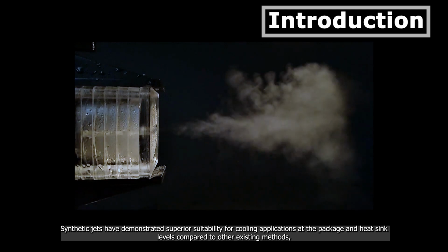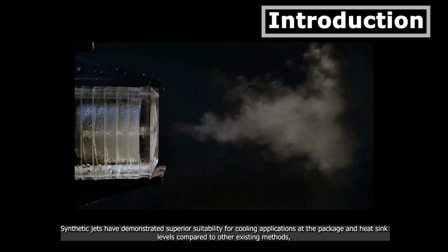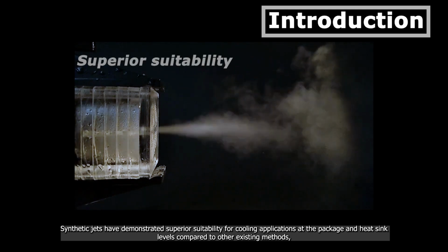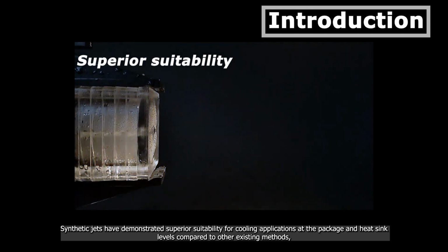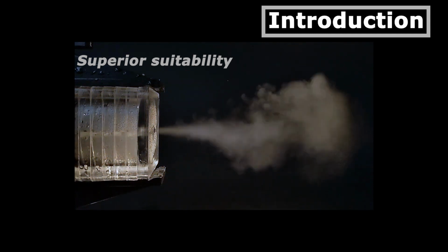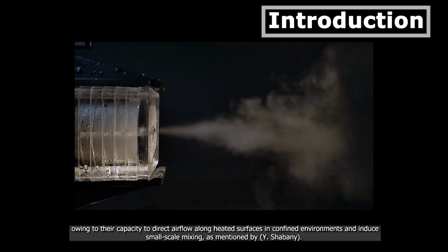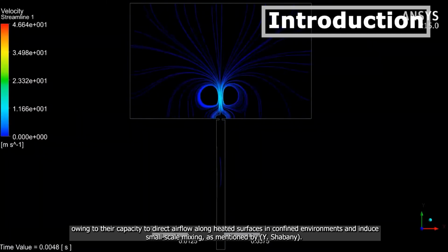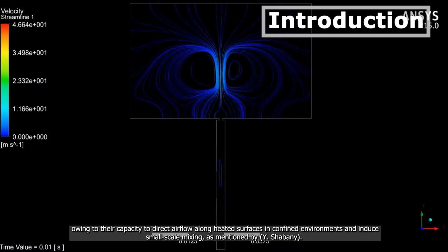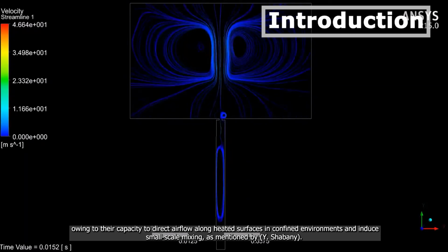Synthetic jets have demonstrated superior suitability for cooling applications at the package and heat sink levels compared to other existing methods, owing to their capacity to direct airflow along heated surfaces in confined environments and induce small-scale mixing, as mentioned by Shabani.